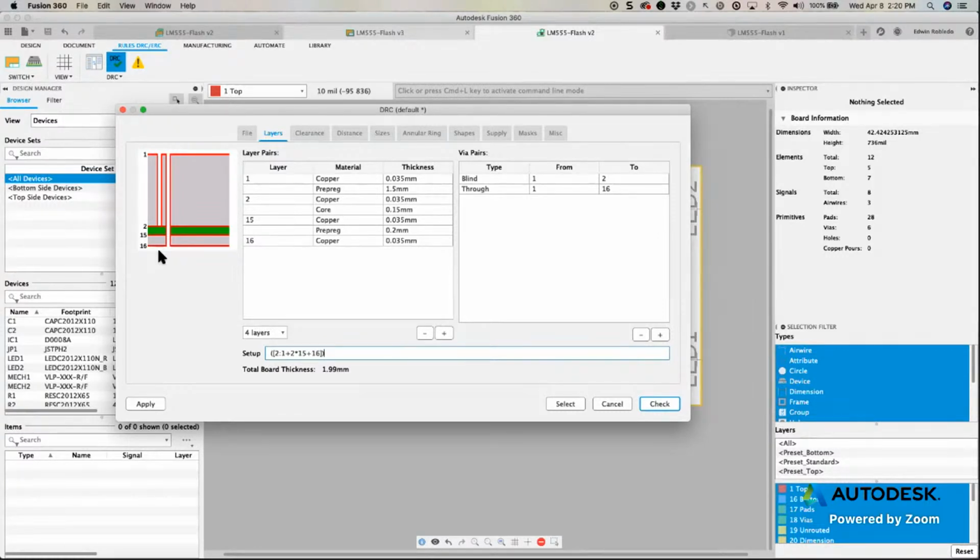So basically, if you just have the through hole, the one that goes through the whole board, they can put all the different layers together, and then there's just one drilling operation. But if there's blind vias, what they end up doing is they have to first drill that 1 to 2, then they put the whole sandwich together, and then they drill again 1 through 16.